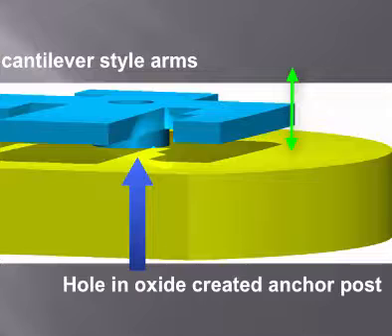So is the polysilicon etched with BOE just like the silicon dioxide? No, polycrystalline silicon is etched with RIE. It's a reactive ion etch. I think our fab, our MTTC, can deposit polycrystalline silicon. How is it etched away if it's underneath the structure?